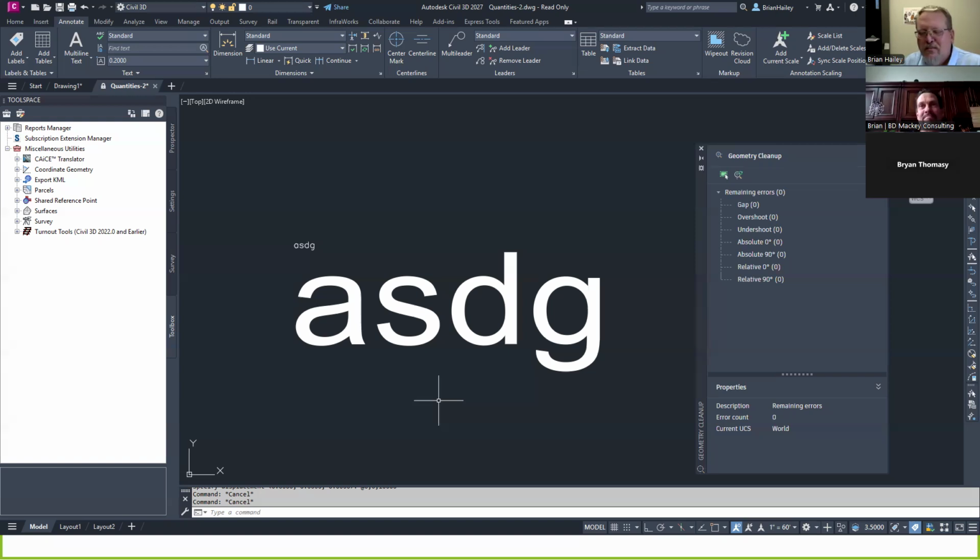Something else that's been killing us is you can't put an SHX font into Revit very well. They don't all look the same when they're plotted. If you've got multiple disciplines using multiple versions of Autodesk items like Revit, Civil and AutoCAD, getting those title blocks to look the same when you're using SHX fonts is almost impossible. So there you go. Hope that answers the font question.